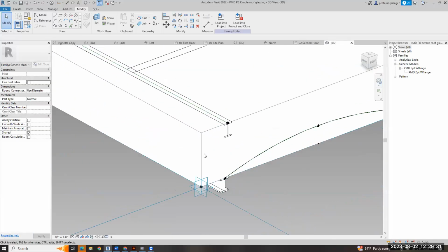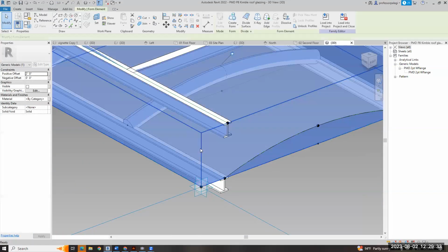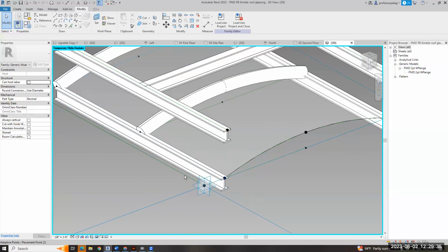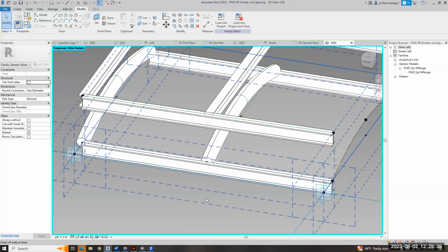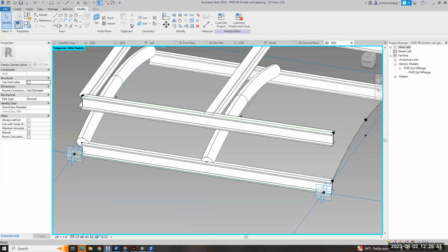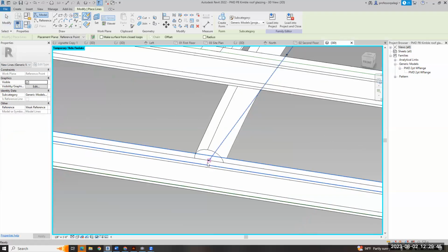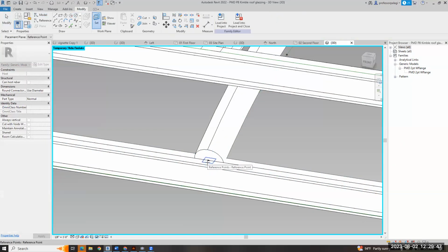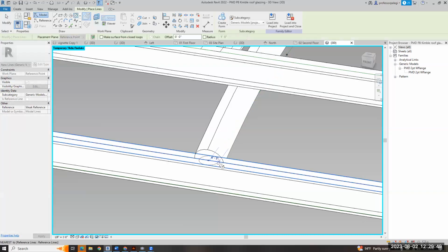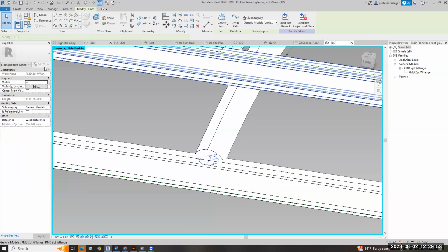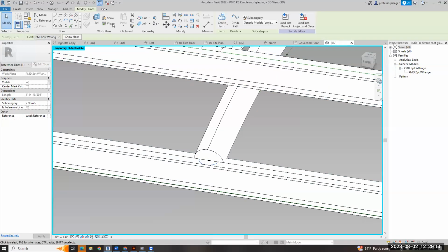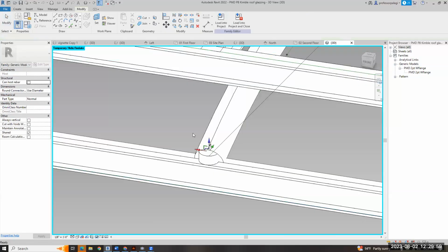I'm going to do it in this one because we got the information here, right? So there's an essence of vertical pipe at each one of these points because it goes down to the beam below and up, right? So I'm just going to go make a pipe, SW tab on that plane. That's maybe 2-inch diameter, and reference line, create form.